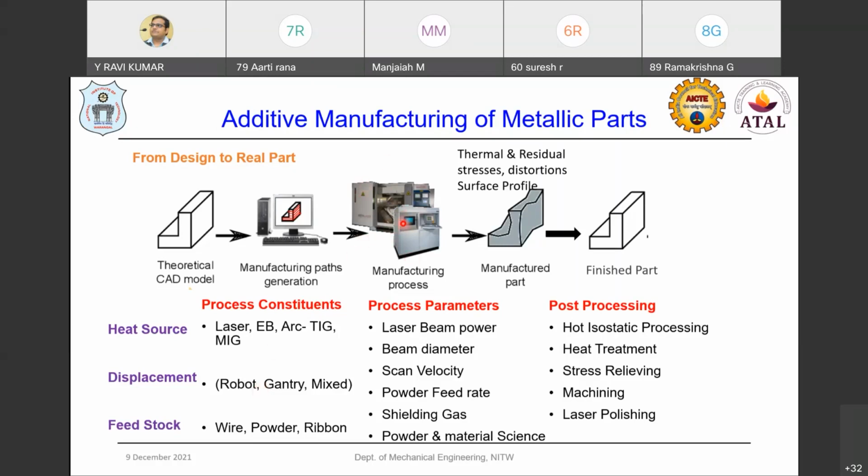You can see here, these are CNC machines. The CNC machines are modified into a laser direct energy deposition process, because instead of the milling head, they adapt a laser deposition head. Here we have the same controlling systems and the same kind of bed systems where we can hold our workpieces. Similarly, the mechanism is there, only instead of the milling head we add the deposition head, which is controlled with z-axis movement, as well as the powder feeding system, along with the laser which comes through the coaxial nozzle.